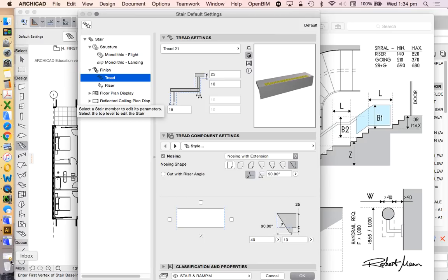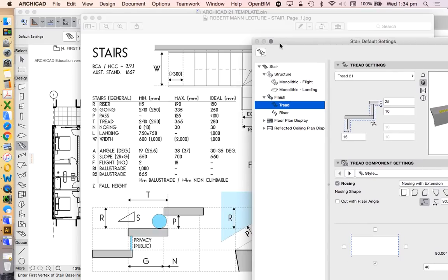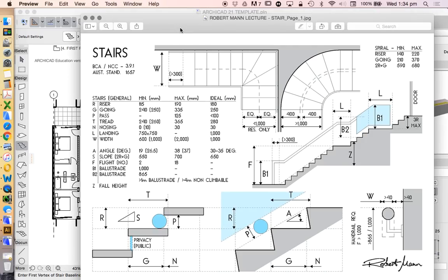When we look at Australian standards, we find that it's quite limited. Australian standards don't really talk about it very, very much. But if we look at international standards for nosing, then they have a lot more information on what is acceptable and what is the legal requirements for nosing. In a residential stair, we often see that nosing isn't considered at all. For an open riser or a timber stair, we have to consider not only the length of the nosing.